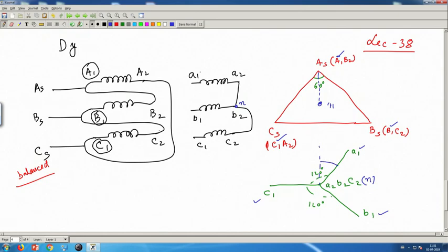So, this is 30 degree. It will be 30 degrees, and therefore, I will say that it is Y D, secondary voltage lagging the primary voltage with respect to neutral by, that I could write as minus 30 degree, or you could write D Y.